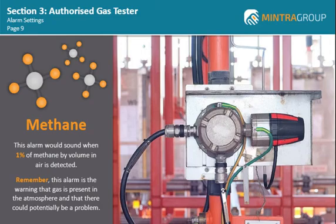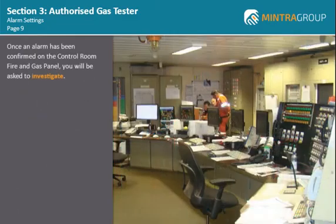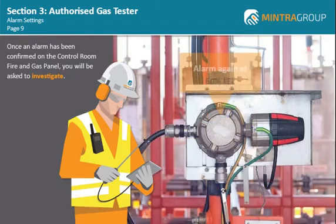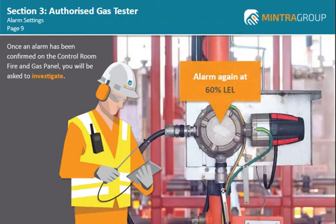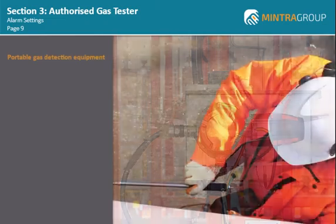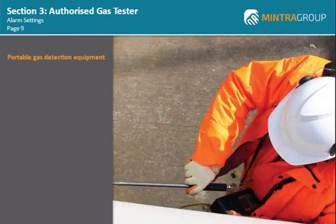Remember, this alarm is the warning that gas is present in the atmosphere and that there could potentially be a problem. Once an alarm has been confirmed on the control room fire and gas panel, you will be asked to investigate to confirm a gas leak or to confirm a fault on the fixed gas detection system. The fixed system will alarm again at 60% LEL, which in methane's case is still only 3% by volume in air. The portable gas detection equipment which you will use will normally be set up with alarm settings between 10 and 20% LEL.